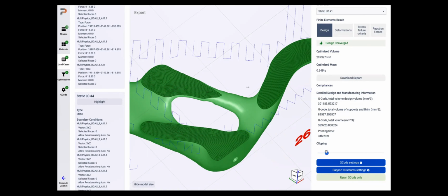A comparison with anisotropic and isotropic, can you please explain the difference? There's a material from Covestro called Novamid ID1030. It's an unfilled material, and there's a filled material, and that's a difference. So we have one which doesn't contain carbon fiber, and another one that contains carbon fiber. And that's what we use to compare the effect of having a filler in there and positioning that carbon fiber in the optimal direction, what the benefit could be compared to unfilled material.